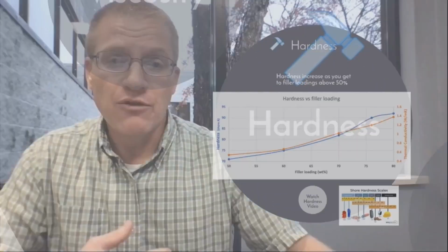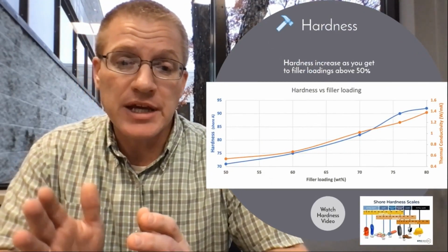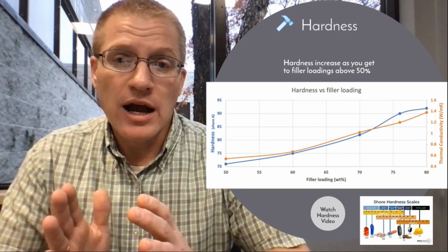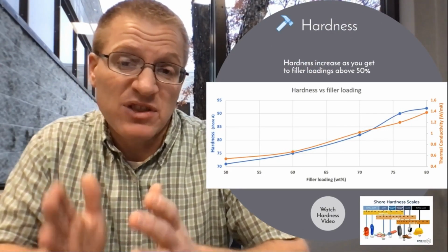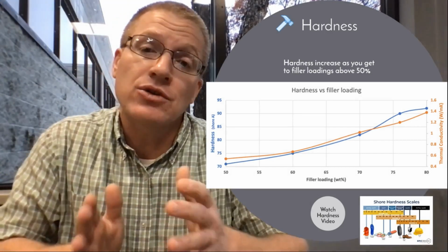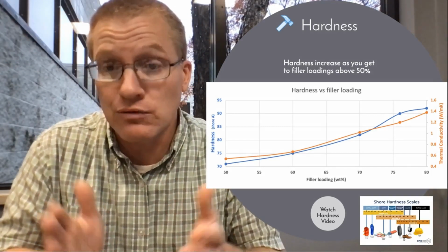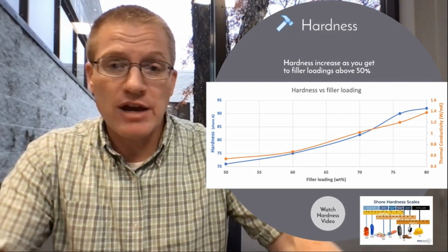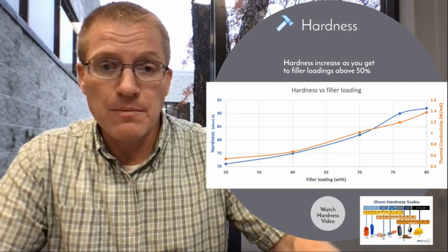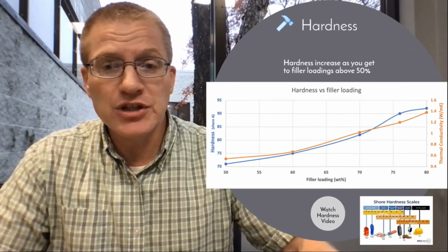So hardness. As filler content goes up, the hardness of the polymer is going to be more and more dictated by, think about it, the rocks that are in it. You have these tiny little rock minerals in there. And as you increase that, more and more of the hardness is going to be an indication of those rocks that are in there, really. So in this graph here, you can see how hardness goes up with filler loading, okay? And as filler loading goes up, thermal conductivity goes up, and your hardness goes up, all right? And this is going to be true for any class.